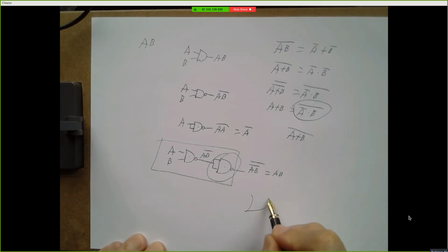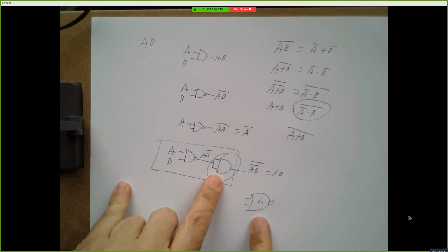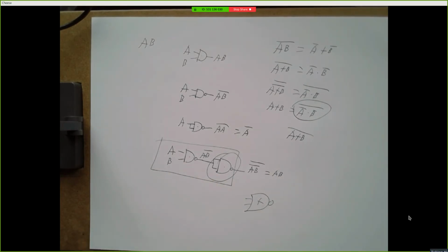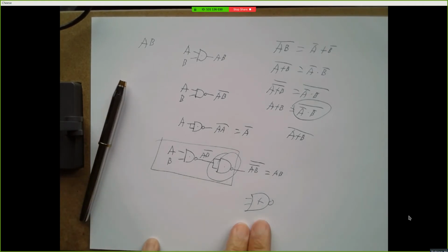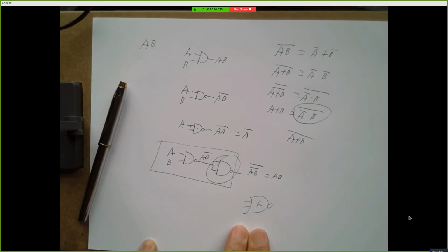And it also turns out if all I have is a NOR gate, I can make all my other gates out of that. So these things are called computationally complete gates, right? If in your parts bin in the collaboratorium you didn't have all those chips, and all you had was a NOR gate, you could still build all the circuits you needed. It would take a lot more work and a lot more wire, but you could still do it. All right, so let's take about a 4 or 5 minute break, and then we'll start putting together some circuits along the lines of what you're going to do in your traffic controller. Come back in about 5 minutes.